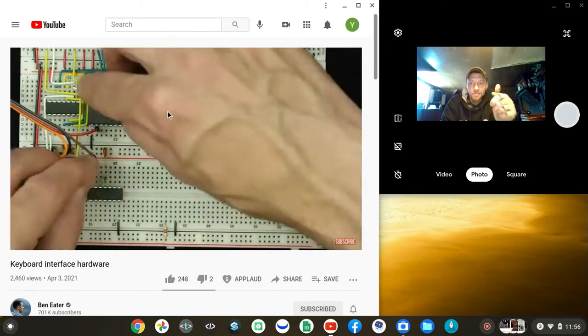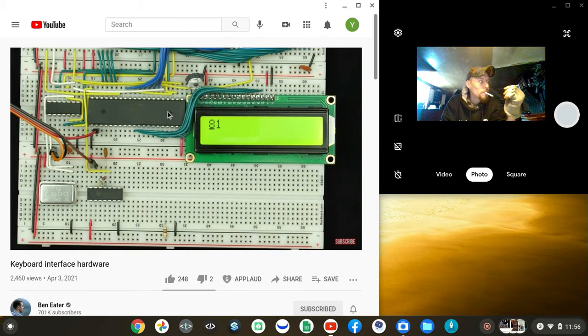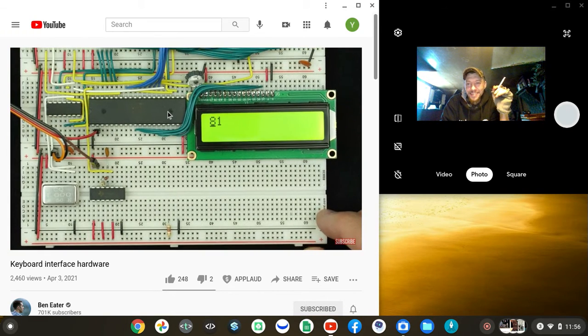And then replace this jumper. And it's always a good practice to tie unused inputs of gates in a row, rather than leave them floating. And then I'll feed the data signal from the keyboard into a shift register, just like I did in the last video.